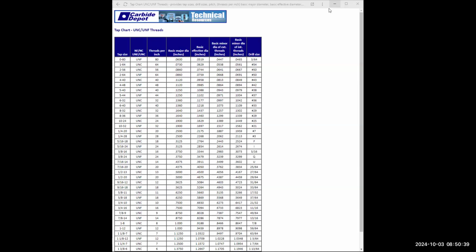What we can do to get rid of some of this clutter is I'm going to show you a neat trick here now. You can do trim, right? And you can just come in here and click on all these lines. That's probably the easiest way for you to do it. There's another way that's easier, but I don't want to confuse you right now. I'm getting rid of all these lines. After I click on trim, it's allowing me to do this. Okay, it's trimming the lines for me.